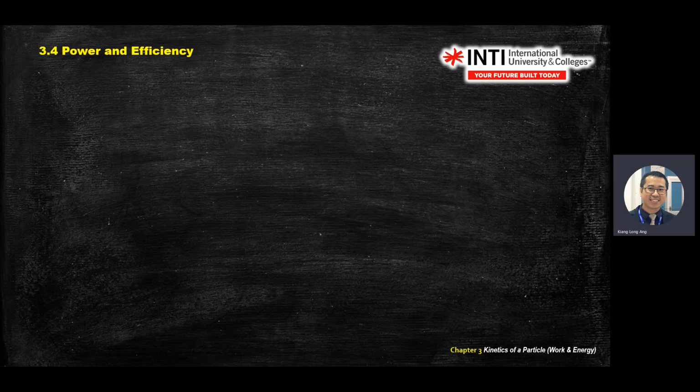You rearrange this. This is called the principle of work and energy, or you can write it in the positive form: T1 plus the change of work equals the energy at your end station, or station 2. This is called the principle of work and energy. And the benefit of using the principle of work and energy is that you can find your V very fast.